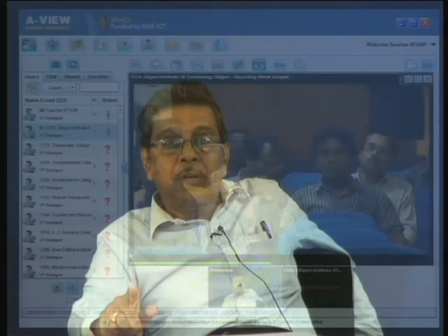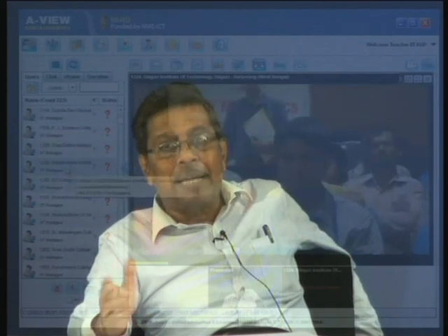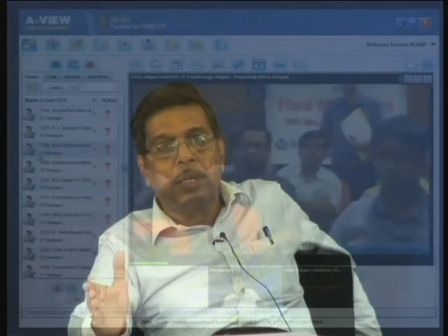So this is made in a way that when the water comes to the rotor or the runner of the turbine, it is in the stator or the nozzle. For example, in an impulse turbine, the entire pressure is converted to kinetic energy and it is expanded in the stator up to the atmospheric pressure to have the maximum kinetic energy at the outlet. So when it strikes the blade, the pressure is atmospheric and uniform, so there is no question of pressure change.